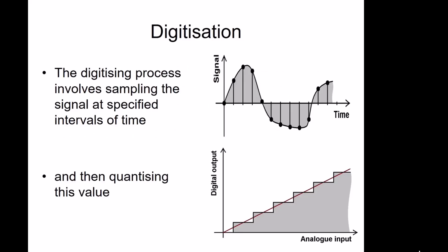When you digitize, it involves digitization in two axes. You digitize with respect to time, so you take points at discrete time intervals, but these points are also quantized in value, so you do not get a continuous signal. These will be in step format depending on the level of digitization.